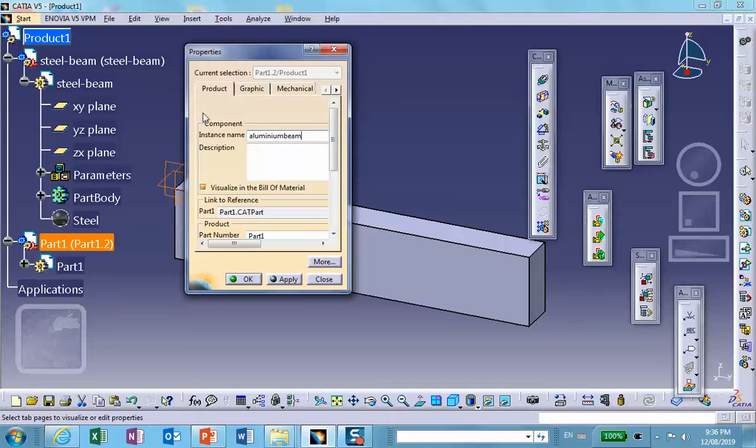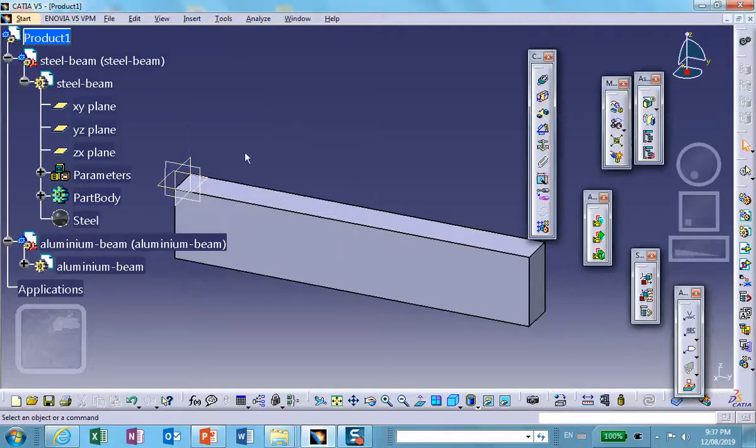Okay, aluminium beam. English pronunciation or spelling, actually, yeah, spelling. So aluminium beam. Okay, and all it is is a line. For beam elements, we just define a line and then mesh it with beam elements. So I'm going to draw that line here on the top face of this aluminum, of this steel part. Okay, so let's get into it.